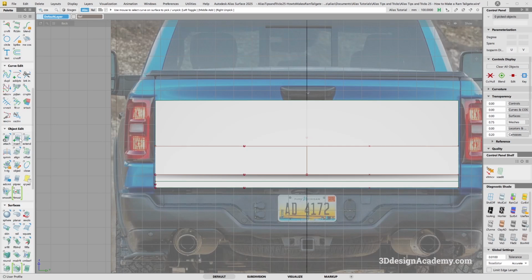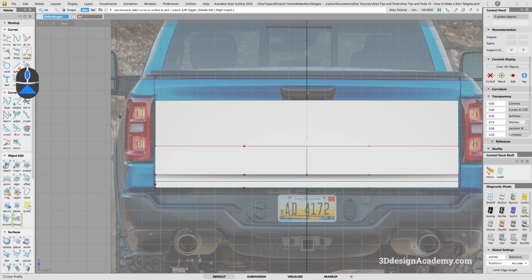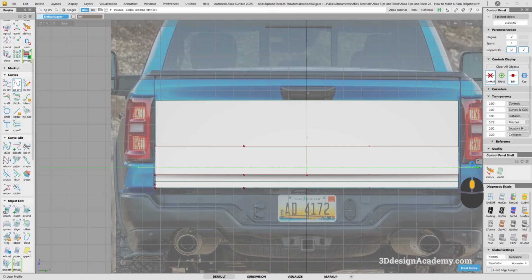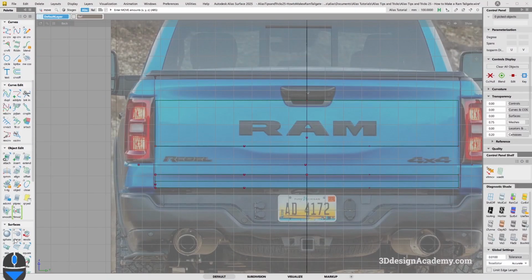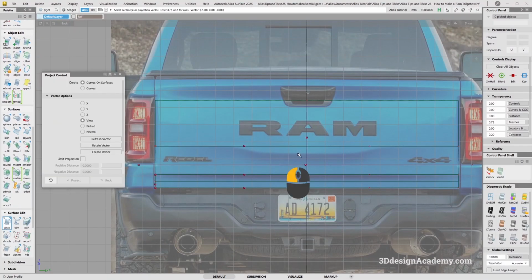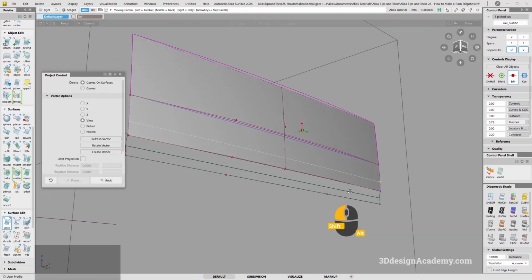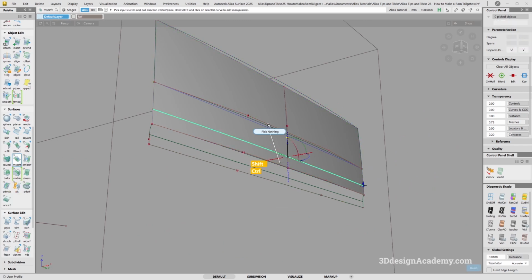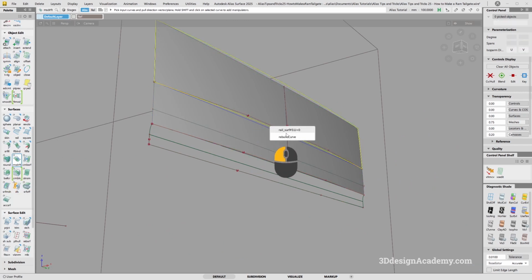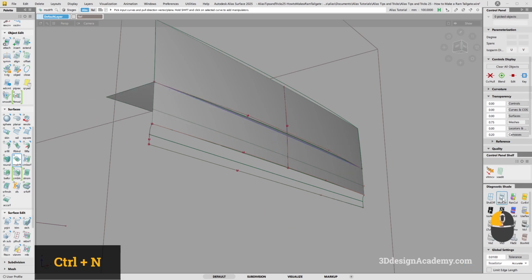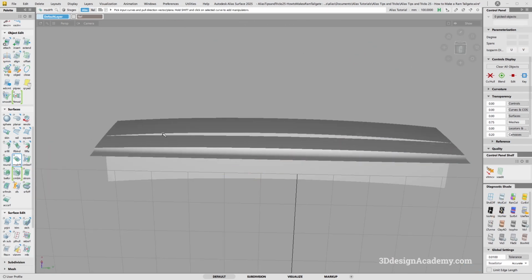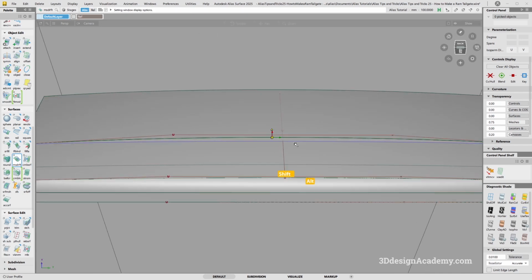So what I'm going to do is, well, let's actually use a COS. I'm just going to strike a curve over here. Now I am going to shape it so that it actually matches the card like this. But just to demonstrate this concept of having consistent thickness, let's use a draft tool for now. If I were to put just a straight draft, you will see that this distance between this one and this one over here is very, very consistent, which is really nice.